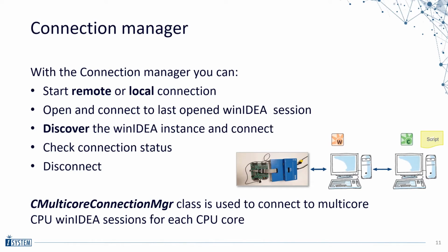The connection manager creates a connection to the WinIDEA session. It can establish a remote or a local connection. A script is executed on a remote PC in the case of remote connection, while WinIDEA is installed and the blue box is attached to the local PC.